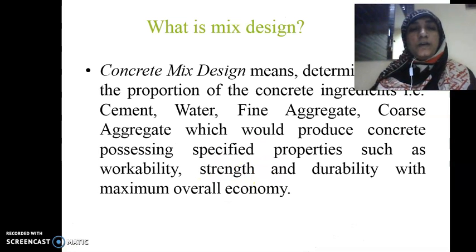Now moving further, what is mix design? Concrete mix design means determination of proportion of concrete ingredients. What are the concrete ingredients? Cement, water, fine aggregate, and coarse aggregate. These are the ingredients of concrete, which would produce concrete possessing specified properties such as workability, strength, and durability with maximum overall efficiency, and this is termed as concrete mix design.